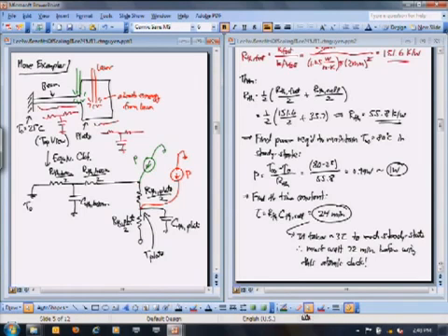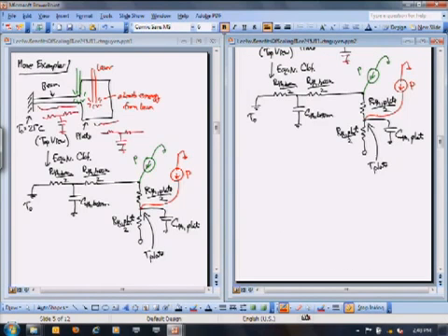Take a look at the geometry of this. Look at the beam, look at the plate. The beam is much smaller than the plate, which means what is much smaller than the plate's? Thermal capacitance is, right? And so you can neglect that thermal capacitance there. Okay? On the other hand, the plate is much larger than the beam. So where does the beam dominate over the plate? In the resistance, right? And so you can knock out these two here, also neglect those two, to the point where this whole thing just boils down to the following circuit,